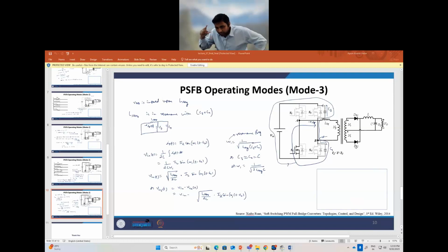have you considered the resistance corresponding to the full load case, or the resistance corresponding to the light load case? Full load case. Okay, because in the totem pole you have this zero crossing problem. That zero crossing problem will become more prominent when you go to light load condition.